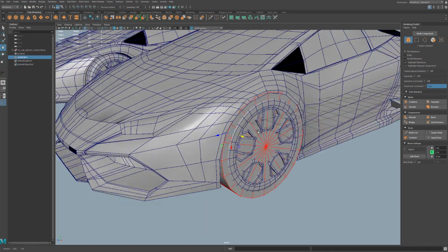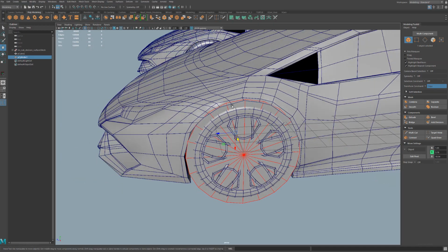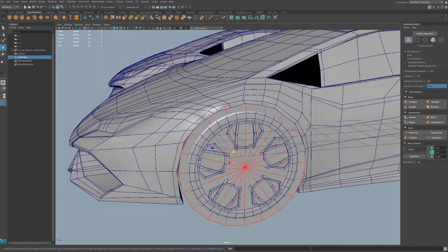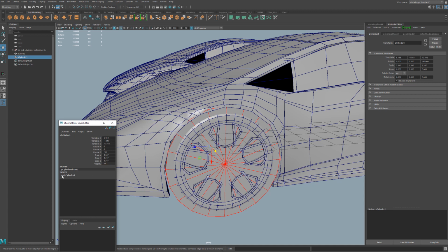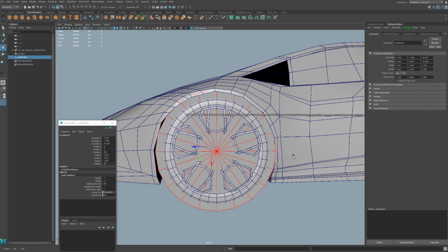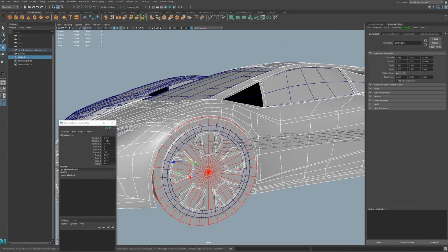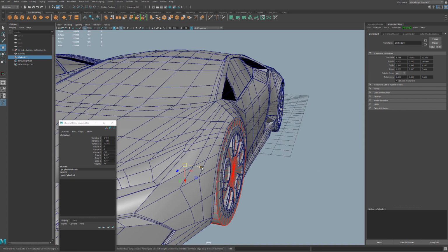So this is going to give us a good idea of even vert spacing. Obviously, by default, these things come in at 20, I believe. Right? And obviously, we had 22, and that wasn't even the whole thing. So we're probably going to have to dense this up a little bit. So let's try something like 32. So what I'm going to do with this cylinder, just make sure that it's relatively flat with this, give or take.